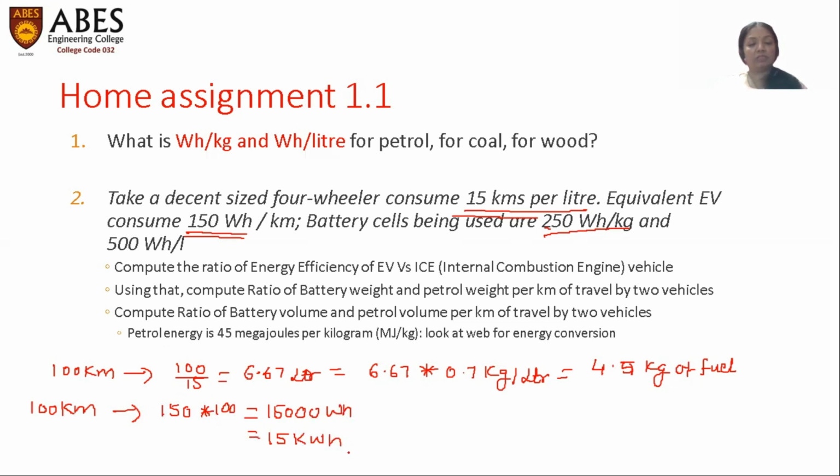I hope you remember the basic unit of electricity, that is 1 kWh. So it is 15 kWh. Now, you see that the energy density is 250 watt hours per kilogram. So corresponding to 1 kilogram, there is an energy of 250 watt hours. So what will be the weight of the battery for it?